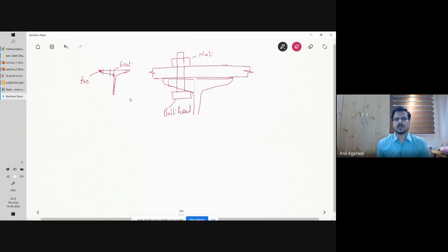What will happen is that the bolt head wants to sit on this surface, and this surface is not aligned properly with the bolt head, and there is this gap that you can see here, right? That gap will cause an uneven stress distribution on the bolt head. As a result, the bolt has to bend, or the bolt head will have to undergo non-uniform stresses, and tightening the bolt becomes very difficult in this situation. You can see the screen, right? You can see the drawing. Please confirm.